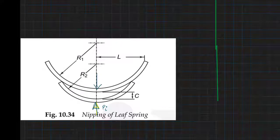In order to equalize the bending stresses in both groups of leaves, we make the leaves in such a way that the radius of curvature of these two groups will be different before assembly. During fabrication of the individual leaves of a leaf spring, they are so fabricated that the radius of curvature of both groups of leaves will be different.